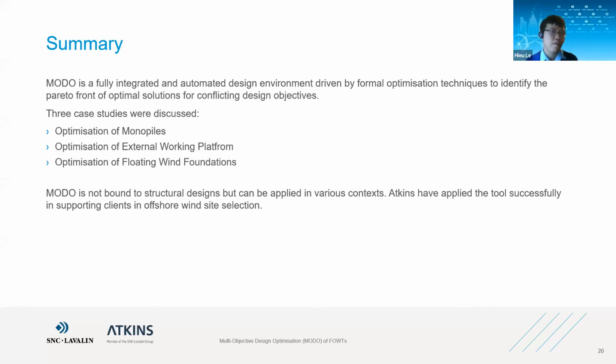Yeah, I think one of the cases we use a surrogate model is to help with the prediction and reduce the number of simulations that we have to run, but we would not trust it. The values we get from the surrogate model, we still run it to make sure that it's actually there. And it's close, but it's not exactly that point. But yeah, never use a surrogate model for the answer. It's only for prediction.